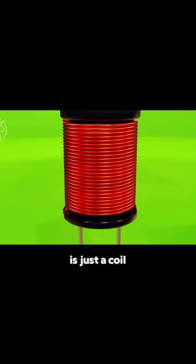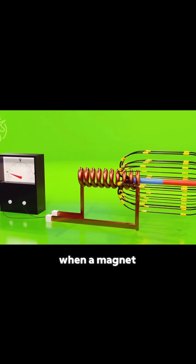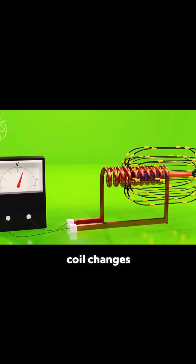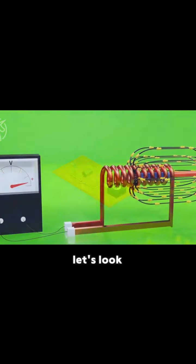Its main structure is just a coil of wire. Here, let's recall Faraday's law of electromagnetic induction. When a magnet moves near a coil, the changing magnetic flux induces a voltage, generating current. Similarly, when current inside the coil changes, it creates a changing magnetic field, which in turn induces an opposing current. Let's look at it in a real circuit.